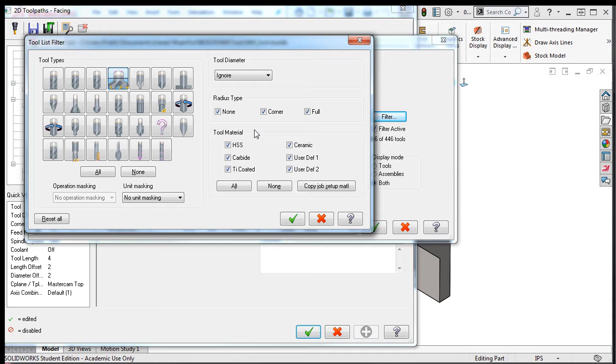There are several factors to consider when making this decision. First, what tools do I currently have in-house to choose from? I'll assume I have all possible cutters. Then the horsepower of the mill, as larger tools will require more horsepower, and the overall size of the rectangular shape I'm milling. Since I don't recall the size of this part, I'll use the right-click options to help me calculate the size of the cutter I should use.